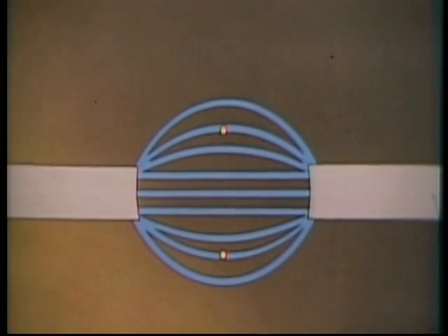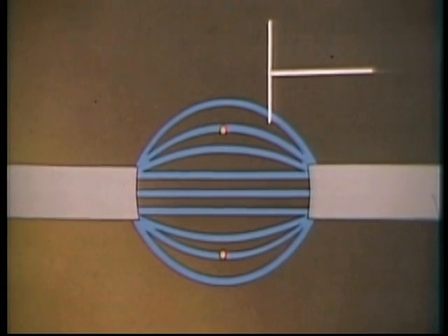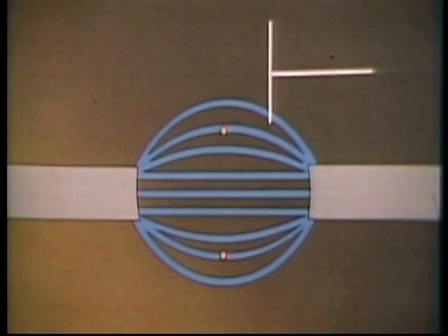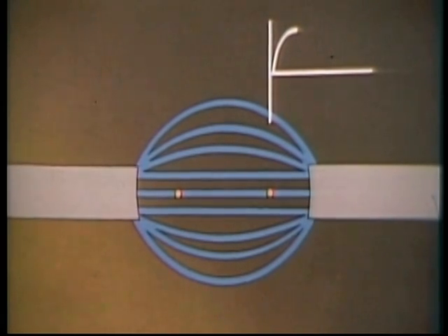At the beginning of the rotation, the AC voltage graph shows us that the induced voltage is 0. The conductor hasn't started to move, so no voltage has been produced. When the conductor starts to rotate, the line on the graph shows us that voltage is increasing. The voltage reaches its maximum positive value when the conductor is at the 90-degree point, 1/4 of the way through its rotation. That's the point where the conductor is cutting through the maximum number of flux lines. It's moving through them at right angles.